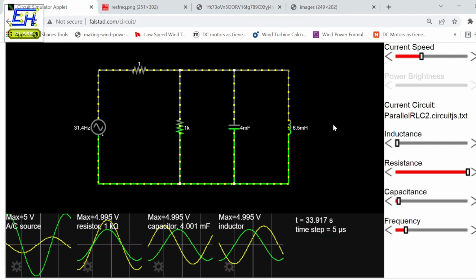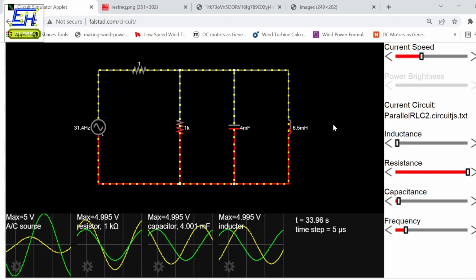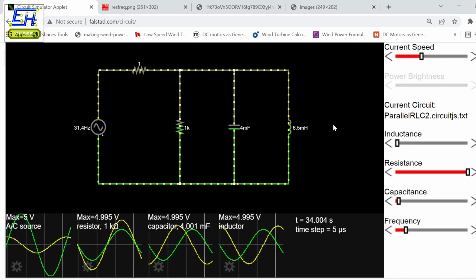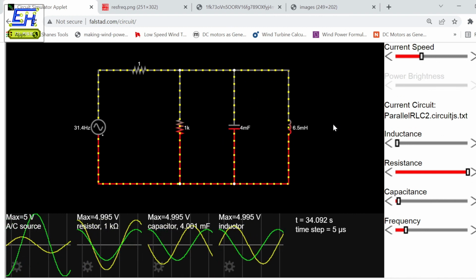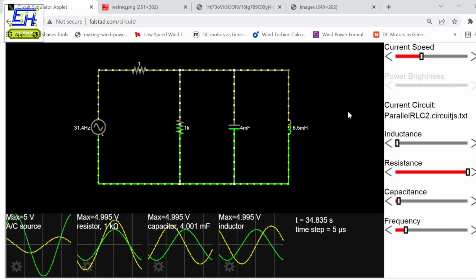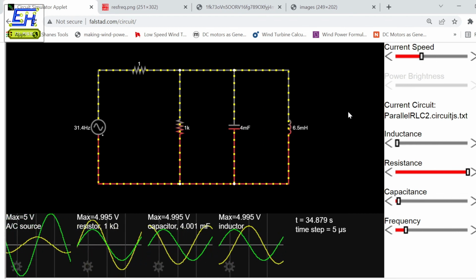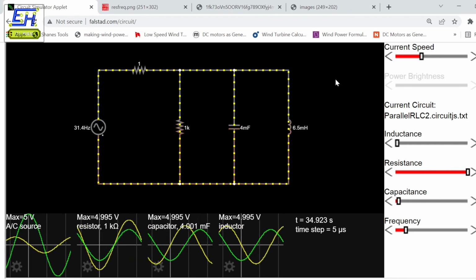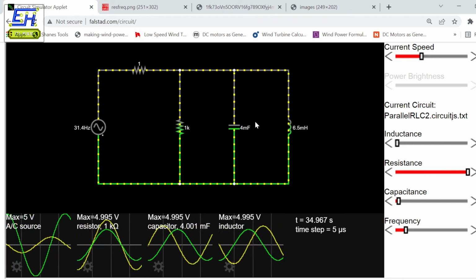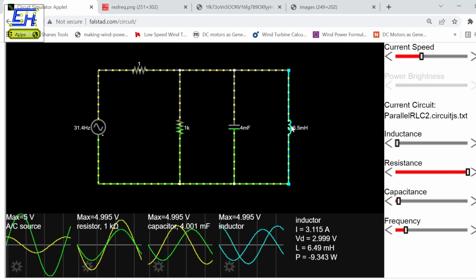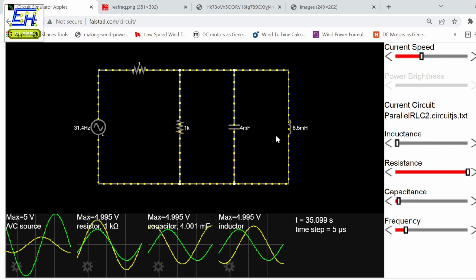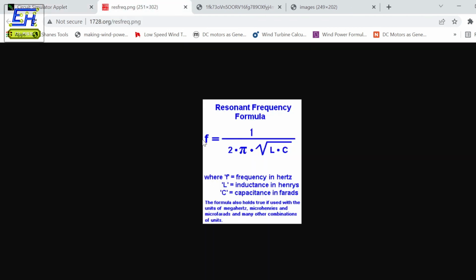Overall we can say that these circuits, series RLC and parallel RLC, behave as filter circuits. They either accept or reject a particular set of frequencies. And the last, most important thing to remember is that be it a series RLC or a parallel RLC, the frequency of oscillation is determined only by these two elements themselves, the capacitor and inductor, or this LC tank circuit. So the frequency formula will be the same for both: the resonant frequency f equals 1 upon 2π root LC.